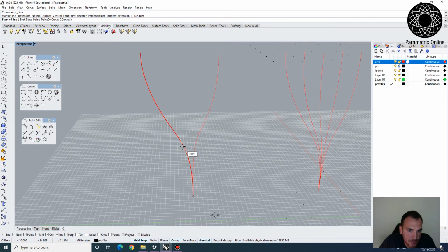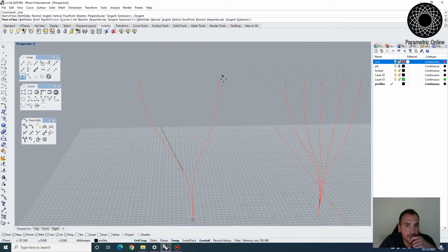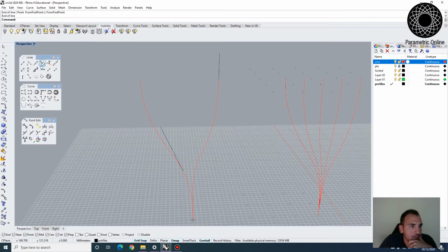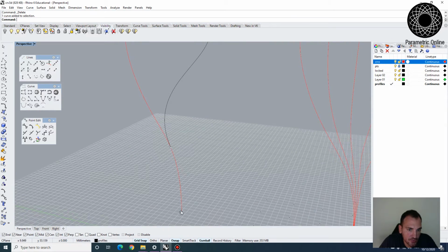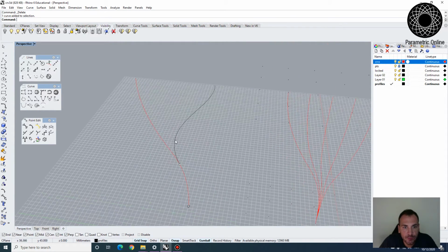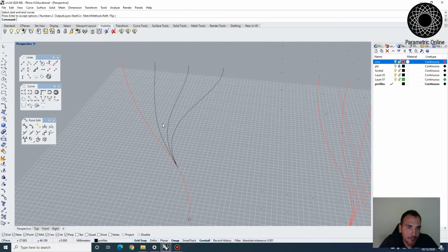So I'm going to do a tangent from curve, choose this line from first line, and then do a handle curve editor, and do it here. I also needed one there too, so let's do that one too. So this last configuration, I'm doing it such that we have a splitting condition, right? So this guy has basically a continuous profile all the way up to this point, and then from that point it's going to split into 4 directions. And I can split this curve at this location, and then we can do tween. And I'm going to move these curves around.